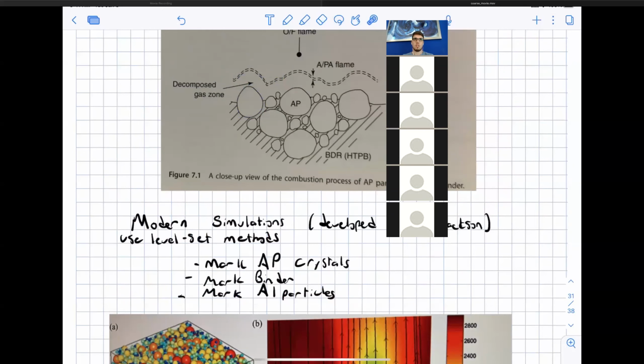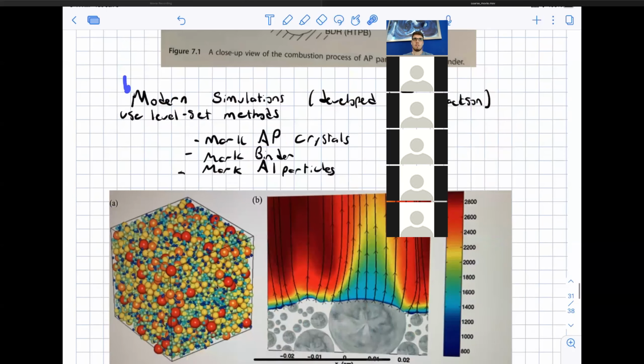And so not only is there thermal and chemical reaction based erosion, but if you have a heterogeneous propellant, there's also mechanical erosion that you need to worry about too. Even if you don't have particles impinging on the surface, you have shear forces that, if there's a strong cross flow, are trying to rip out all the AP crystals and things like that. So heterogeneous propellants are much more complicated, and you need to go to really advanced 3D simulations.